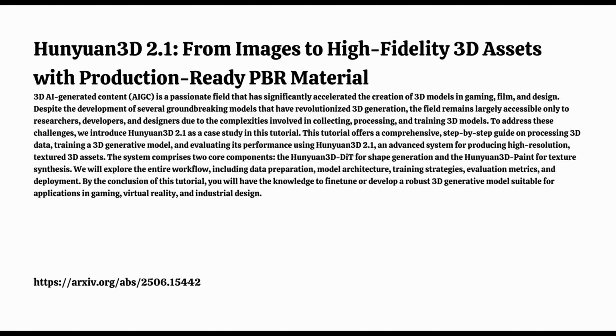It generates what are called PBR material texture maps, specifically albedo, roughness, and metallic maps. PBR stands for physically based rendering. It's basically teaching the AI how light actually behaves in the real world, following principles like the Disney BRDF model. So instead of just a flat color, it understands surface reflectance, how shiny or matte something is, how metallic it is. That's what gives it that hyper-realistic look, adhering to industry standards for rendering.